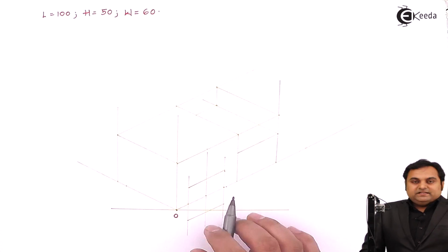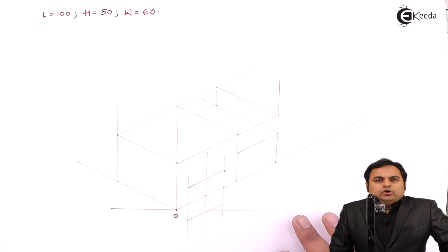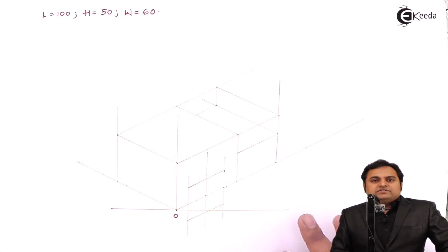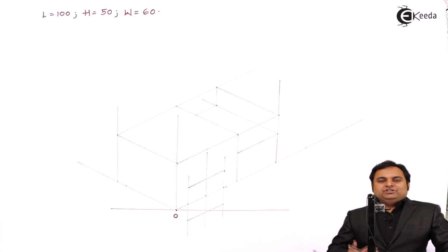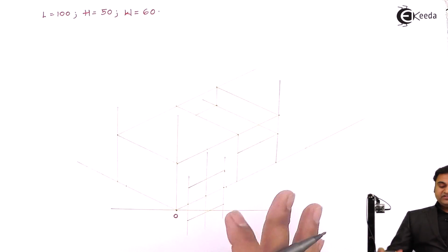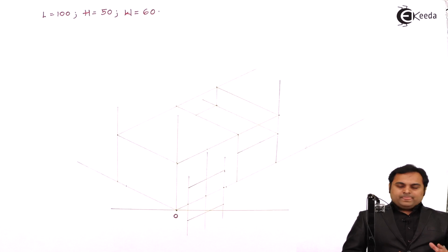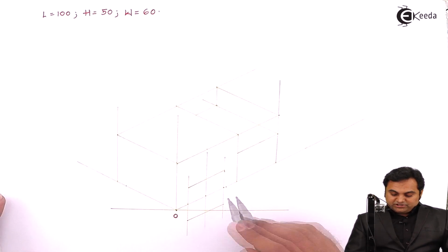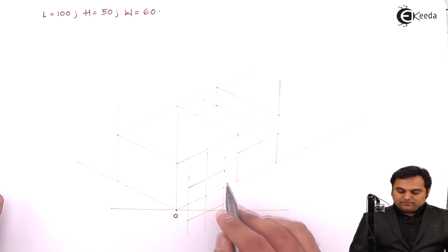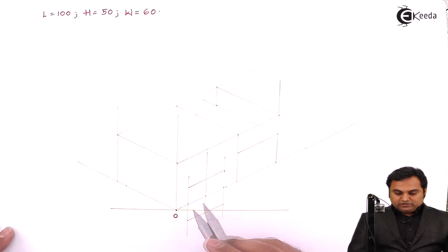So this is the parallelogram, and here I am explaining the method, that is how to draw a semicircle if it is an isometric drawing, because here we cannot take the radius or diameter directly and draw the semicircle because the surfaces are inclined, so that semicircle will also be inclined. And for that, the procedure is, after drawing this parallelogram which is having sides equal to the diameter, I would be drawing the longer diagonal here.